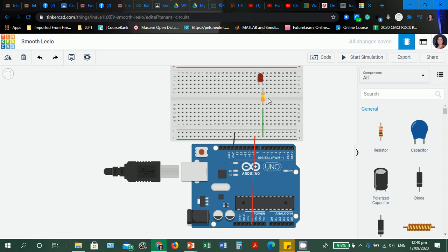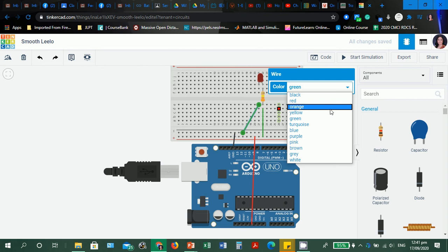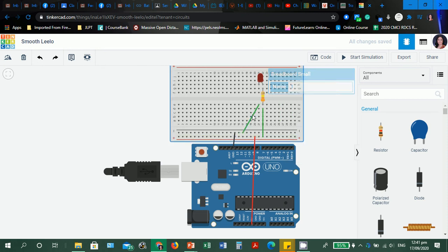So for you to, for example, this is possible because the resistor is the one connecting the point here to the point there, so there's still a connection. So for it to work, for example, if you click it in here, and then for the negative, it will not work because there is no connection between this pin and this one, because the middle separates the points of the breadboard. Okay, so again, let's click it in here, and then we have to delete it.